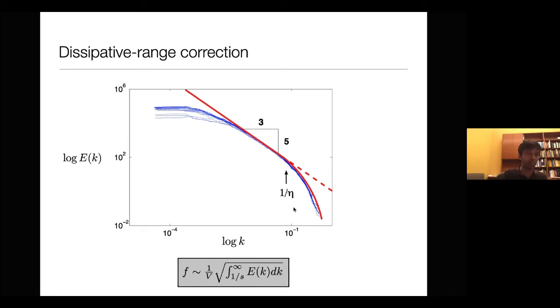The model that I use is called the power model, but you can use a very simple exponential, and the results are very similar. So I substitute this new form of the spectrum, inertial range with dissipative correction, into this expression of the spectral link, and I simply calculate what the friction is and plot it as a function of Reynolds number and different roughnesses in a Nikuradse-like plot.